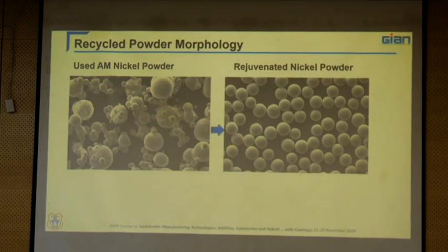And once we follow all those aspects, we use those agglomerated powder particles to make very spherical powder particles with the vacuum induction atomization or plasma atomization process. If you see the regenerated nickel powders, 6K Additive has proved sustainability in these powders. Worldwide they are the leading manufacturers nowadays. The used powders they are buying and selling at a minimal cost, because this will be very equivalent to your original powder particles. Highly spherical powder particles, with more flowable properties, very good compaction, very good apparent density, and all the aspects required in these powders. That is possible by the atomization techniques. With the rejuvenation we are able to do it.